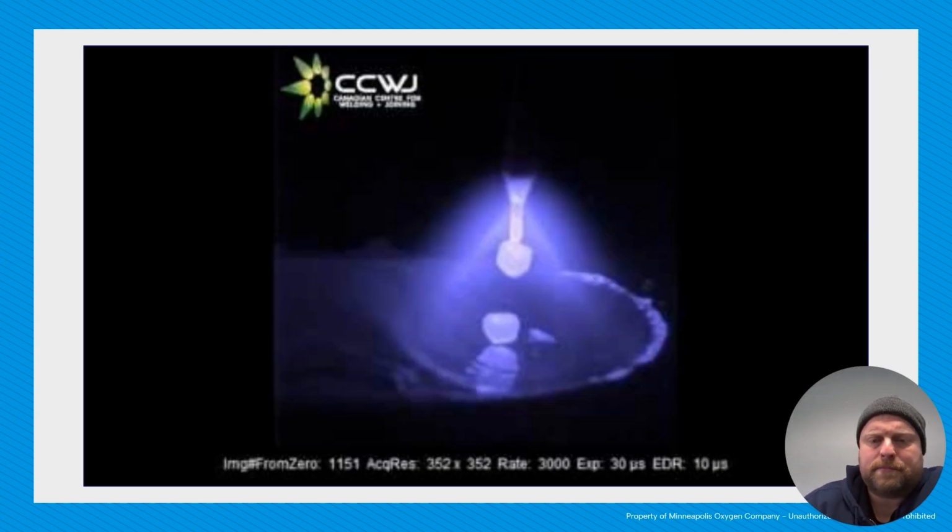So let's look at some spray. So we can see some of the settings here. 400 inches per minute wire feed speed, and I think it's at 30 something volts, so lots of energy. And we can see that cone shape I was talking about, and just these little droplets coming off. So very little spatter. You can see it's very controlled. Tons and tons of energy.